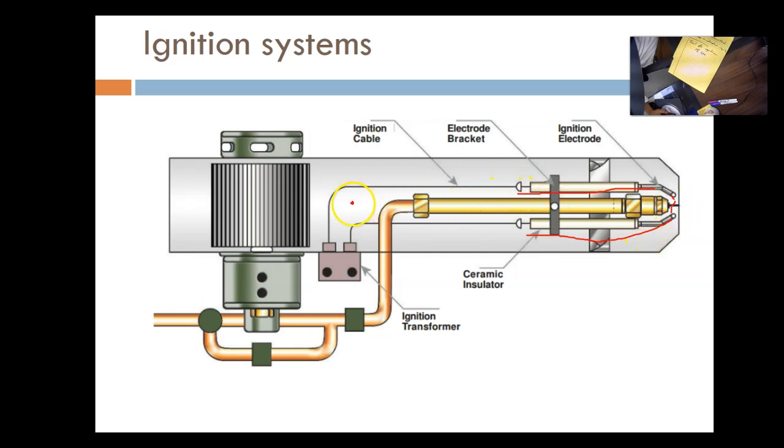And these have to connect to the ignition transformer. We have to make this voltage that goes through these electrodes. And anytime we have any kind of leak of this voltage, we might not have the proper ignition. It's very important to have this set up at the right distance from the plate, the right distance from each other, and the right distance from the nozzle itself. Otherwise, we will lose the power of voltage and spark, which generates heat that is hot enough to ignite the